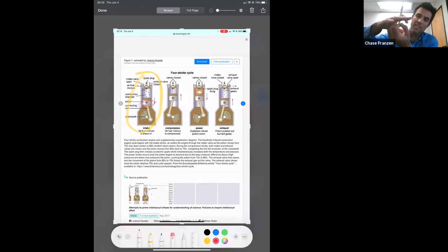So as that connecting rod draws the piston down, that's the intake phase. What's happening is fuel and air is getting sucked into the cylinder, a fuel to air mixture that we control with both the throttle, controlling how much goes in, and the mixture, which controls the fuel to air ratio. We're sucking the fuel and air into the cylinder in the intake stage.